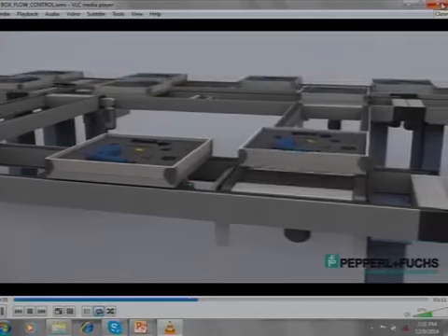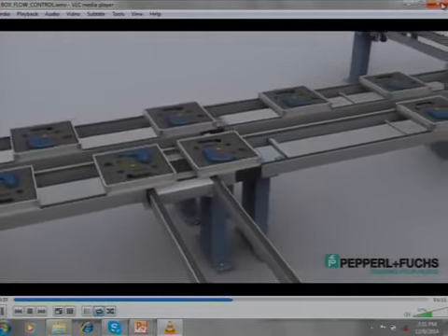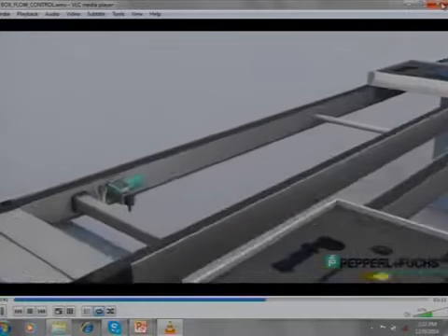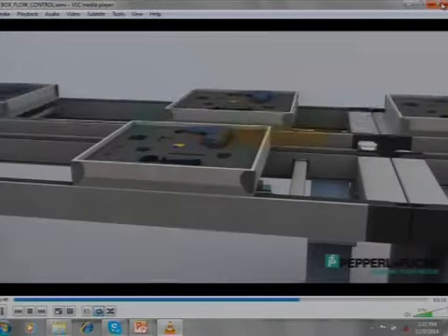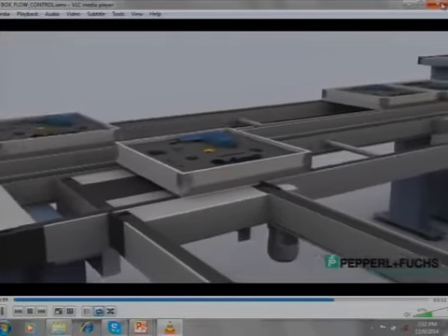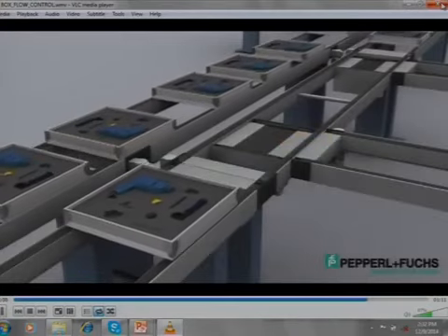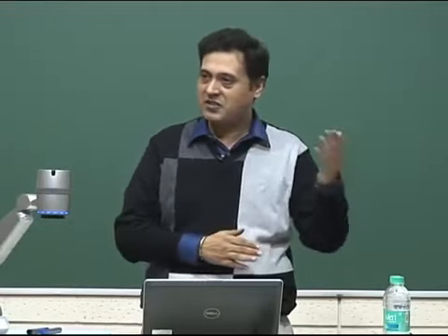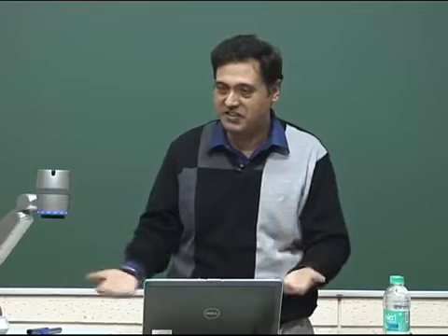So these are all some basic sensors. Now there are certain applications in the industry where you require sensors which have some special features. As I said, industry may not have mild steel as a target every time. The target can change, it can be mild steel, stainless steel, brass or copper. For that purpose there are sensors which should give a sensing distance of 10 mm, for example, with all types of targets. Those sensors are called reduction factor 1 sensors, that means irrespective of the target composition the sensing distance will always remain the same. Your component can change from brass, copper, mild steel, stainless steel, anything, you do not need to change the sensor, the same sensor will give you the same sensing distance.